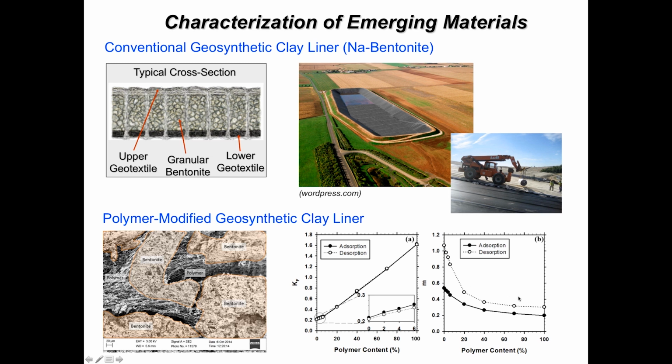So the idea is to be able to use water vapor absorption as a screening tool, basically. If this is a manufactured product, heterogeneity of the polymer within this system becomes extremely important. We don't want spots where there's not enough polymer, perhaps from an assembly limitation, where the polymer within this mixture is not homogeneous, and so it becomes a way to do spot checks on the polymer content. Can we use water vapor absorption to do that, for example? And so these are some of the things that we're looking at.